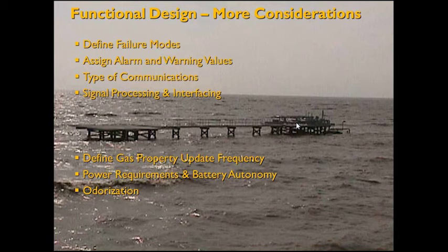One of those other things you want to consider is gas property updates. How often are you going to update gas properties? Do you have a chromatograph? You probably wouldn't set a chromatograph in this installation. You would probably do either composite sampling or spot sampling. But there's a question about, well, how often do you apply those gas properties? And getting that in sync with your other flow measurement is a particular problem.